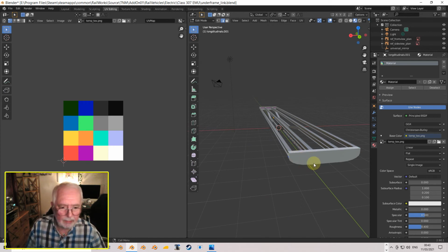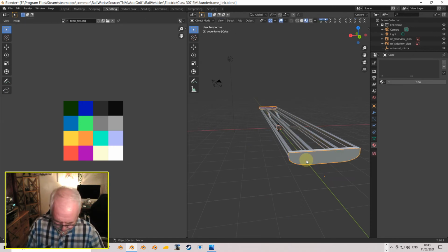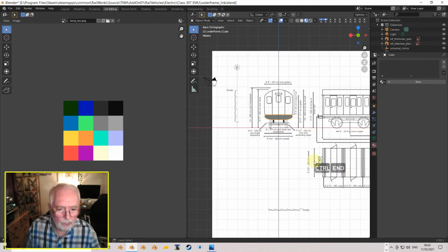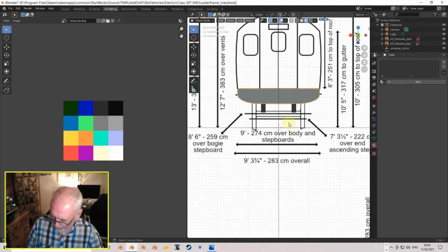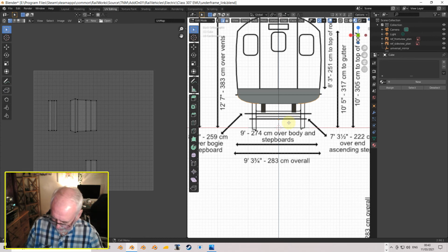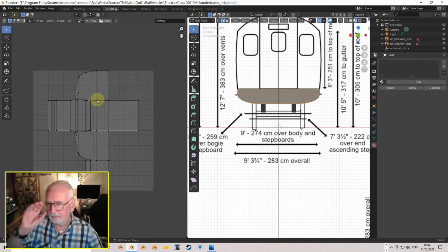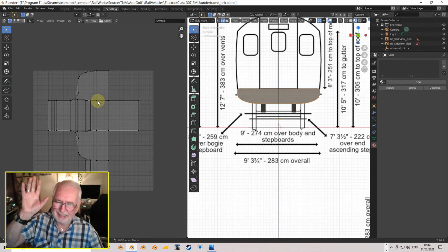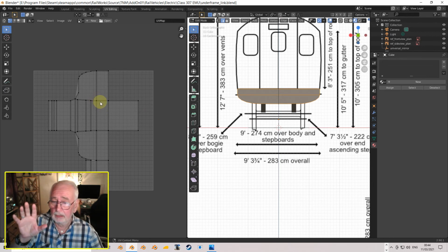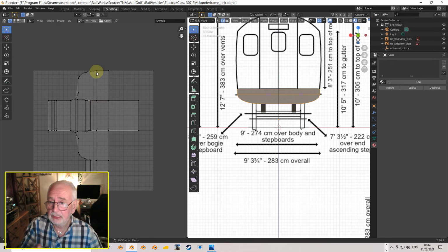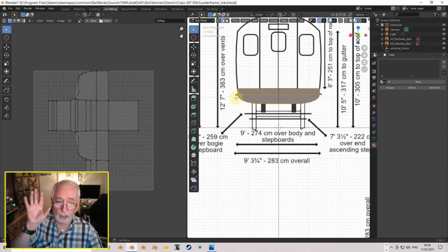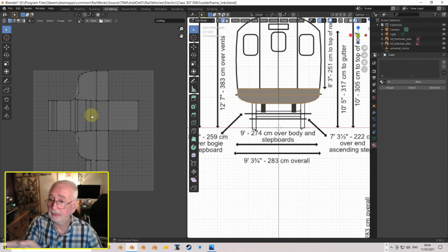And the plate, I haven't named the plate, I don't think, so come front view. Okay, again, edit mode, select all. Now with the later versions, it automatically creates the UV. So I normally go project from view, whereas I don't actually need to because it's already made a UV.